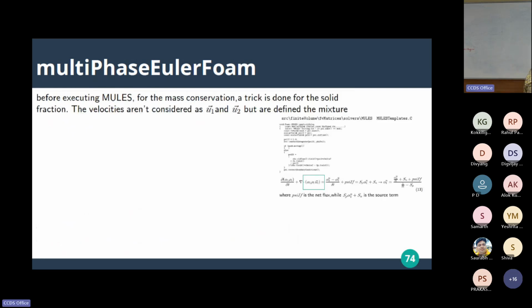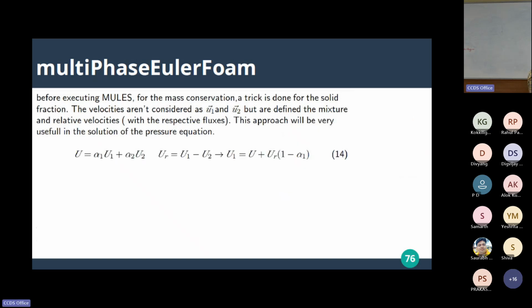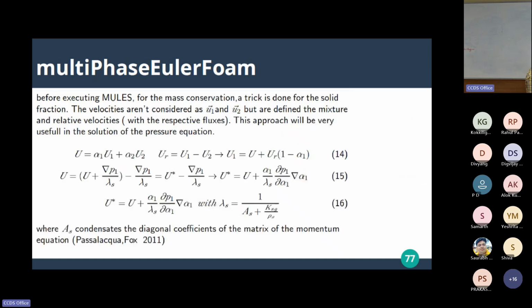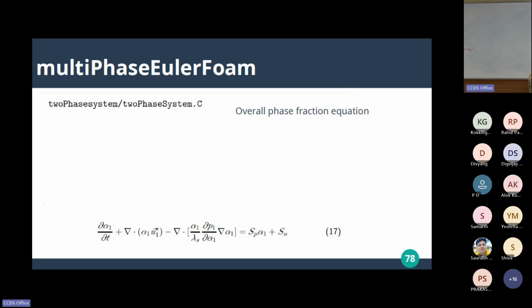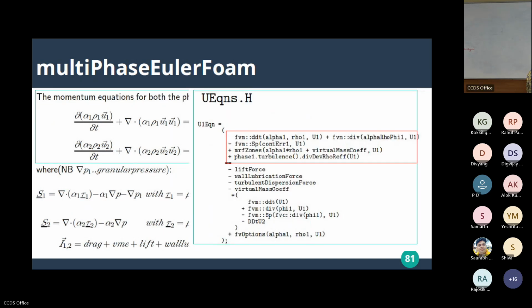Look at it, and once you solve that, velocities are to be approximated. You use that velocity information, go ahead, solve your original momentum equations, club those stress terms or perhaps these alpha terms into your momentum equation via additional force terms, the SP kind of terms.